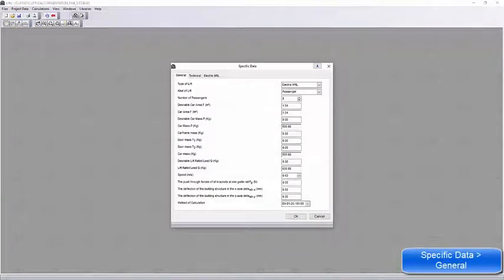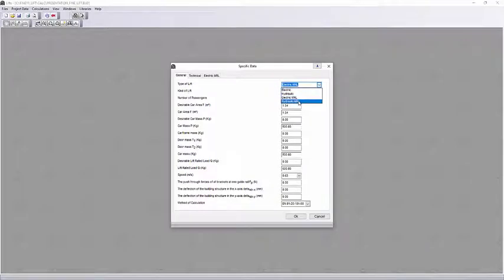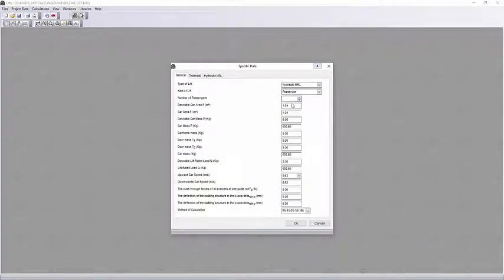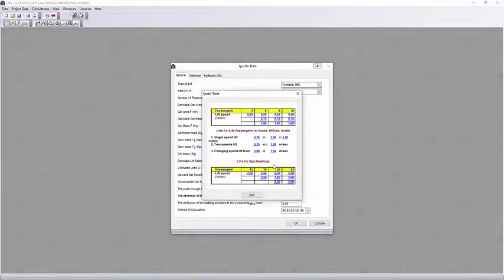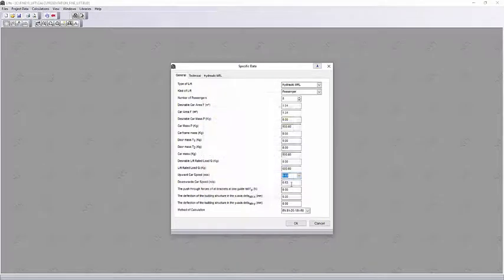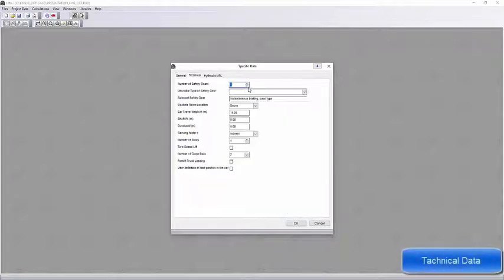In the General Project Data, the basic parameters of the elevator will be filled in. The user can select between electric, hydraulic, simple or MRL lift. The kind of lift can be chosen from passenger, hospitals, vehicles, or goods. Some more data about the car mass and area must be filled in. At last the user can choose between the EN81-1 and 81-20 calculation method. In the next tab, the technical characteristics of the lift will be imported.